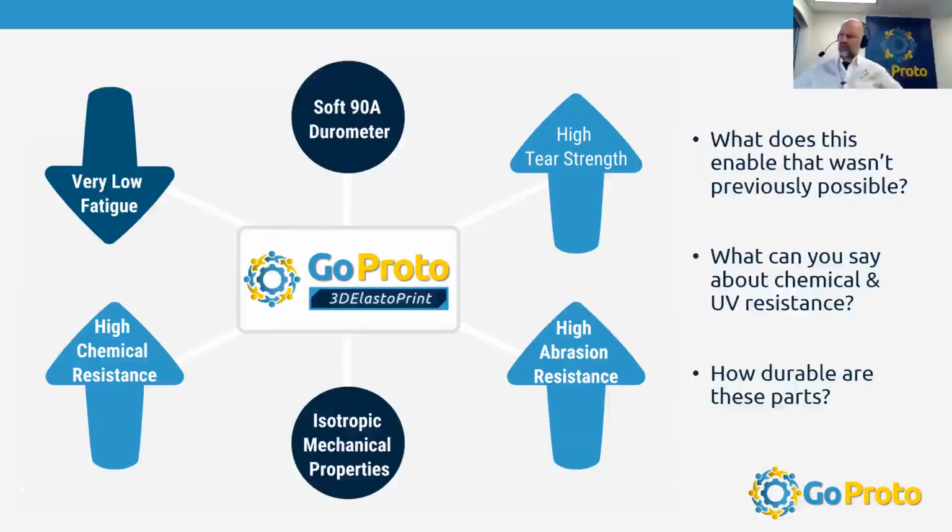I'll also say, thank you, Rebecca, very much. I'll also say from the product development side, I've been in the low volume space for a long, long time where we've made photopolymer parts that are elastomer, i.e. Objet. That is a photo process where it's exposed to UV light to phase change it from liquid to solid. And when it's done printing, that phase change doesn't stop. If you have it exposed to the lights in your office, like the fluorescent lights above me, or like Rebecca said, sitting on your windowsill, it's going to continue to cure, and it'll go from kind of clear or amberish to full on yellow. It starts to look terrible, and then it also kind of crystallizes on the exterior surface. It becomes more brittle. It just continues to change over a very short time.